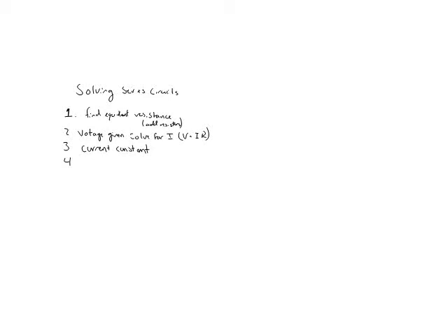And then once you know all the resistances for each one of them, now you know the current for each one, you can use V equals IR to solve for V for each one. So now you'll know the current, the voltage, and the resistance of every single resistor and the total as a circuit. And the last little step that your book doesn't make you do all the time is you solve for power. P equals IV. Solve for P. And I'll show you a grid and how to solve all of this.